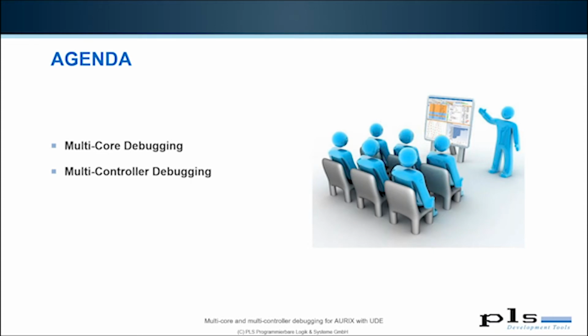So UDE is also able to debug more than one controller at a time. By default, these controllers or MCUs are handled independently. That means that they are not synchronized for debugging. And this works, of course, not in all cases.